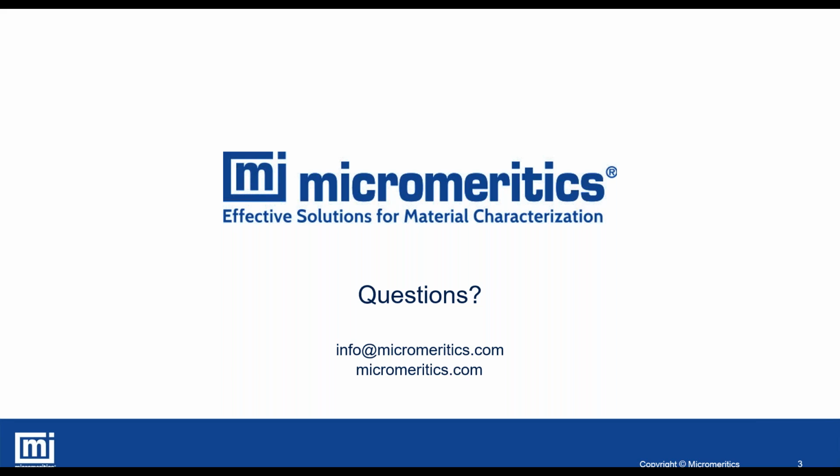I mean, other factors will change that affect its dissolution rate, like its solubility in the solvent, things like that. But you don't need to redevelop the model, assuming there's going to be a different relationship on the surface area. Because you're using PSD as a proxy, if you develop your model on PSD, every time you change your material, you've got to work out what the relationship between the measured PSD and the measured surface area will be.